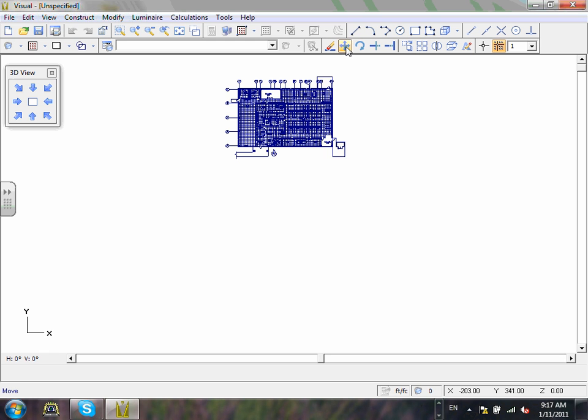Good. I'm going to go to the move command and highlight the area that you want to move. So it's red now. I highlighted it. It's red. Hit enter, or right click. It will ask you for the move base point. Can you guys see the move base point right at the bottom here? When you right click, it activates the move base point. Everybody there?